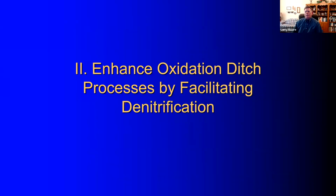All right, so that was a general assessment of how we can use DO control to save energy. Now what we want to do is look at oxidation ditches first, and see how we can incorporate an anoxic period to achieve denitrification, and how that'll help us save energy. Now, what we need to understand is, let's say you have an oxidation ditch right now that is operating fully aerobically. In other words, you may be providing 1.5 to 2 milligrams per liter DO 24 hours a day, 1,440 minutes a day. That's okay.